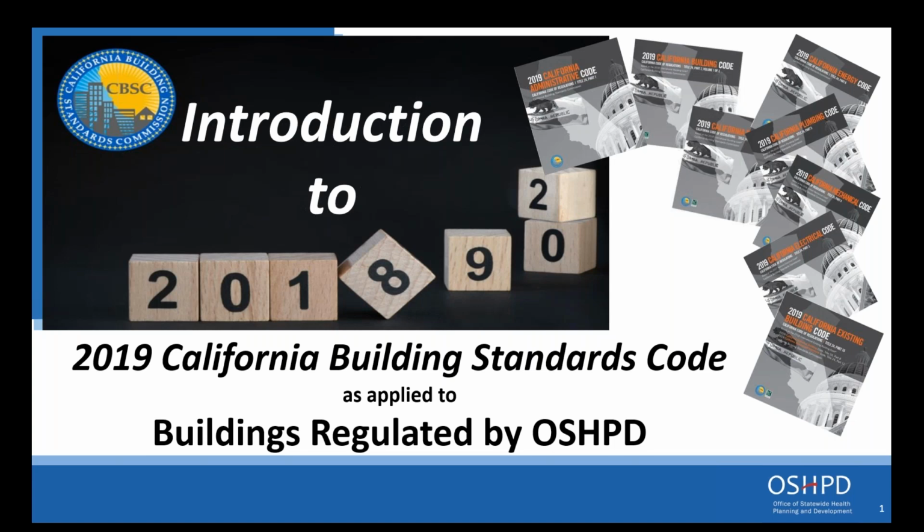Okay. Perfect. I got another one for you, Dave. Question reads, does the code require AC 156 seismic certification for plumbing and HVAC piping systems? You know, it's actually not to dodge that one, but it's something that we have reviewed by our structural engineers here for seismic. Any seismic requirements in model code will apply. And also ASCE 17 modifications that are in the building code that are addressed by our seismic engineers, those will apply also. And there's a list in there.